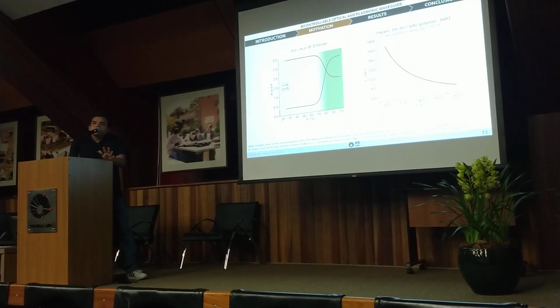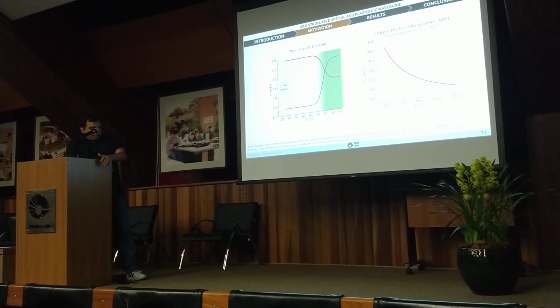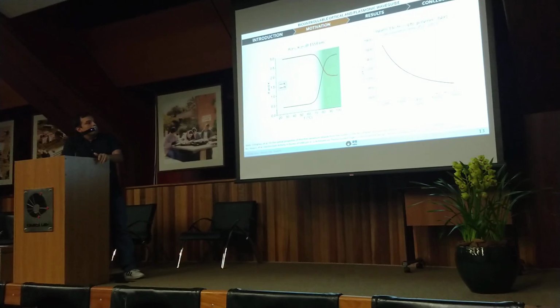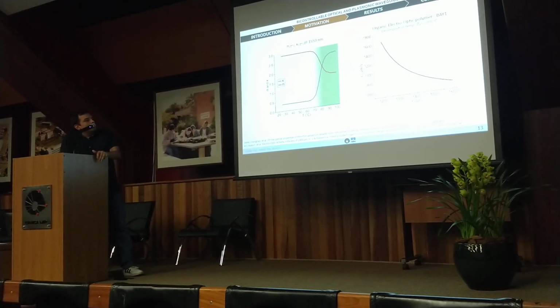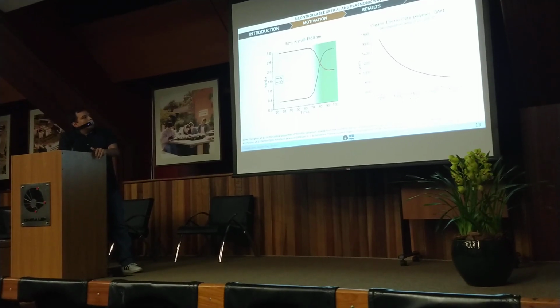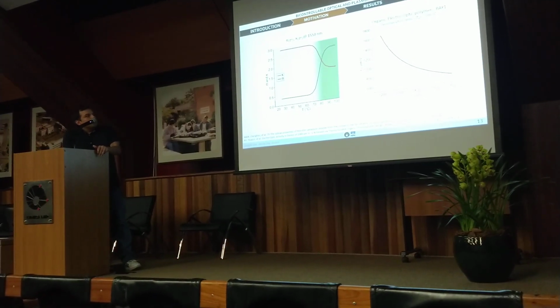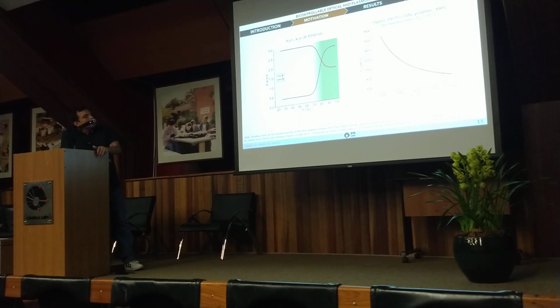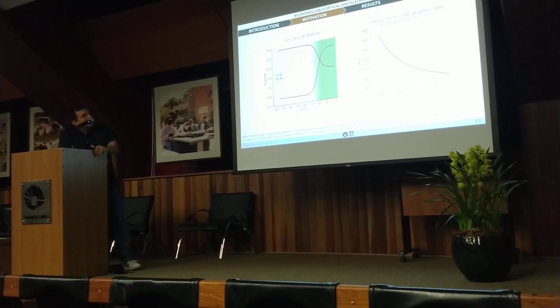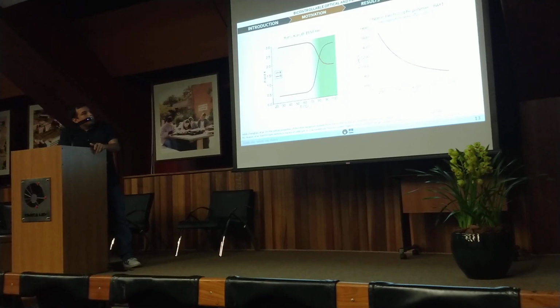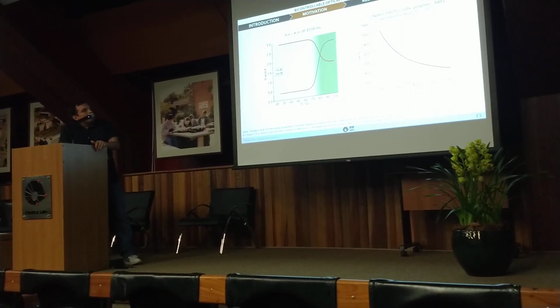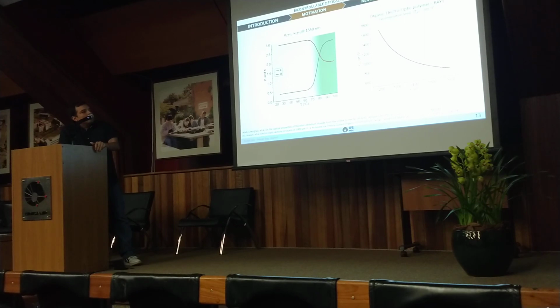Here is another feature of the materials. On the left, you have the real and imaginary parts of the refractive index of this material in terms of temperature, at a wavelength of 1.55 micrometers. You can see that as the temperature increases, the effective index of the material decreases. On the right side, you have the electro-optic coefficient in terms of the wavelength.